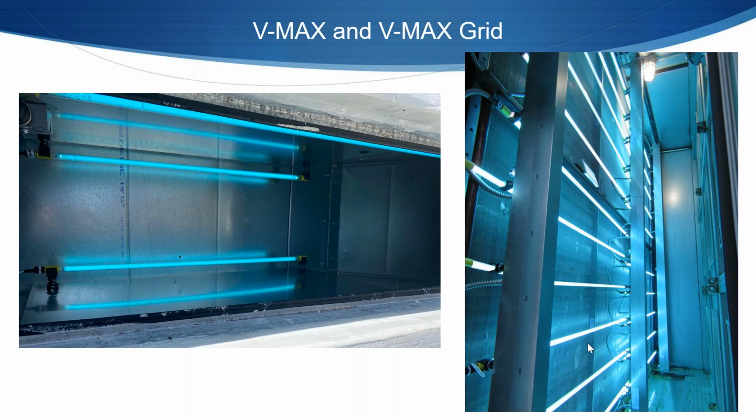So just a note of safety: we need to make sure to pay attention, just like we do with any other piece of equipment from any supplier, any type of technology we're using. We provide fan guards for fans, disconnects for fan sections, disconnects for power, etc. So as with any technology, we need to provide safeties. That means installing a disconnect switch on the door, and often also a power disconnect nearby, so that if they're operating with the door opening and closing, when the door closes, they're not in there with the lights reactivated. So a manual override switch and door switch is highly recommended.